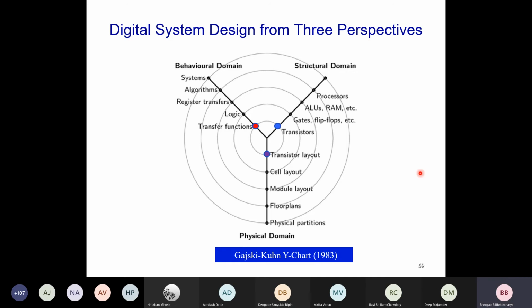So at the bottommost level, for example, you have transistors structurally. That means when you are talking about components, you have transistors. But when you talk about implementation, how the transistor is implemented on a silicon chip, you have different layouts. You have a diffusion layer, polysilicon layers. You have layers one after another. Those layers can be thought of as differently shaped rectangles or depositions of different materials, right? So from the physical perspective, it is nothing but some sort of layouts, the geometry of layouts.